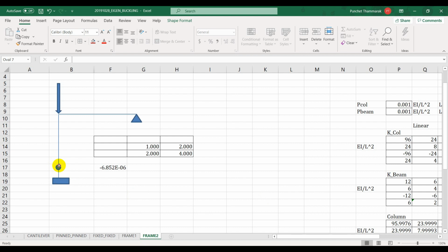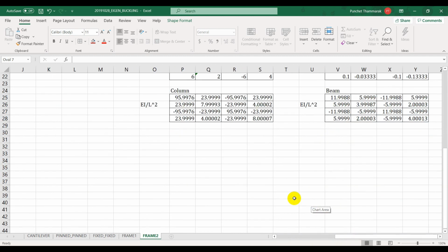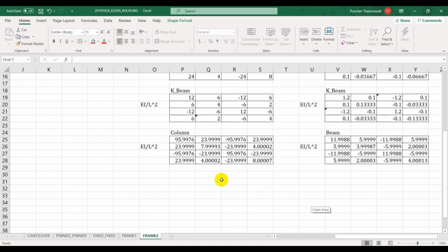So somewhere close to the max, actually not too close to the max, top might be 0.4 and here might be 0.6, because the restraining effect here is not as much as the restraining by the support. Well, anyway, 0.5 will work. It is not that sensitive to this choice of location if it is around the middle.